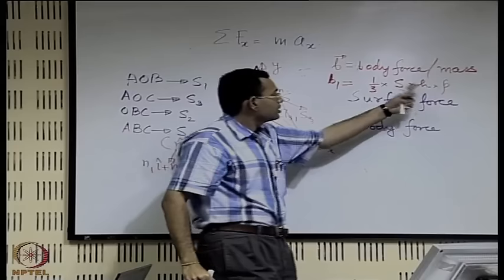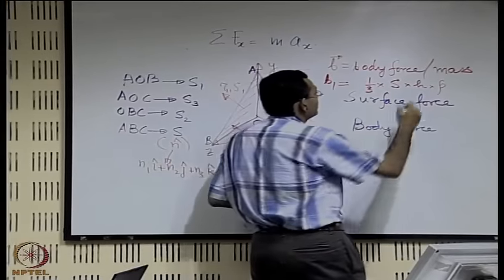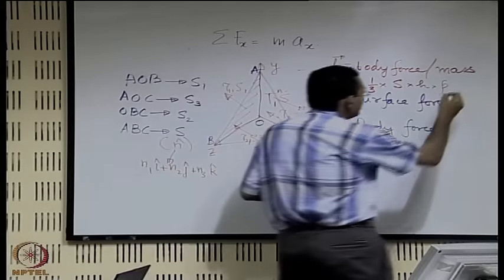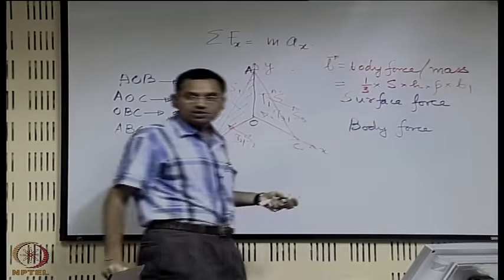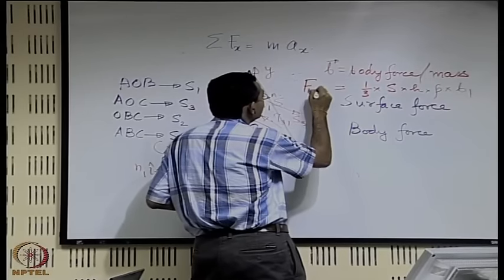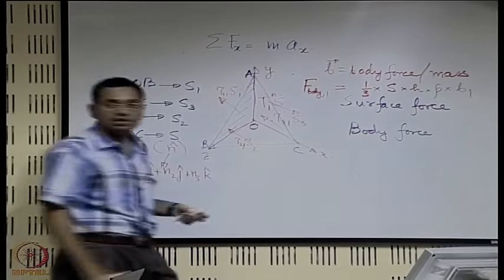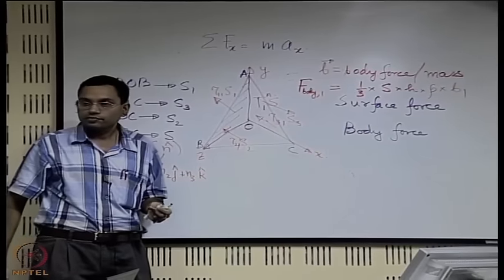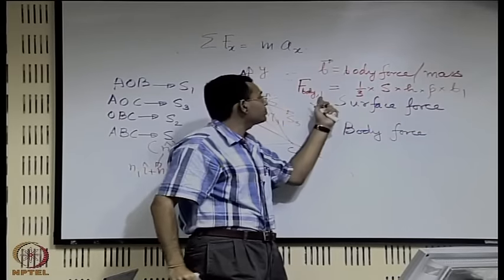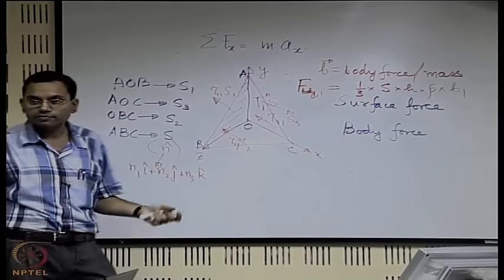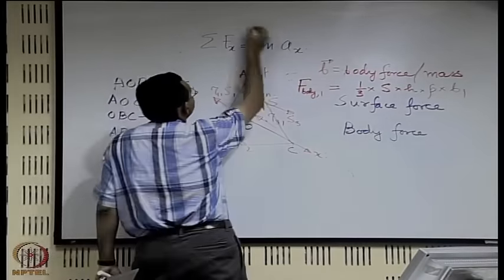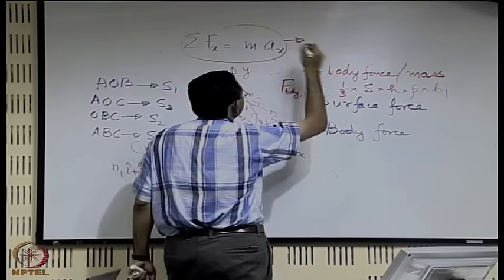This is the volume. Mass of this you multiply it by the density, say rho is the density. So this is the mass, and this multiplied by the body force per unit mass along x will give the total body force along the direction 1 or x. So the product is the total body force along x, right. So we write Newton's second law of motion, this particular expression. Now we write the forces.